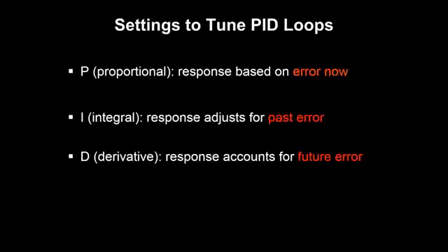So another way to look at this is that we have with proportional a response that cares about the error right now. With integral, we're concerned with the past error, and with derivative, we're looking at the future error.